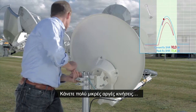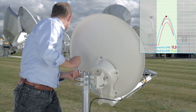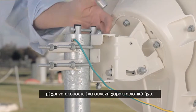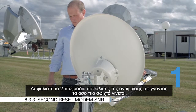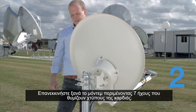Now you make very small movements. Slowly, very slowly, until you hear the continuous tone. Lock off the 2 azimuth locking nuts as tight as possible. Now you must reset the modem again, waiting for 7 heartbeats.